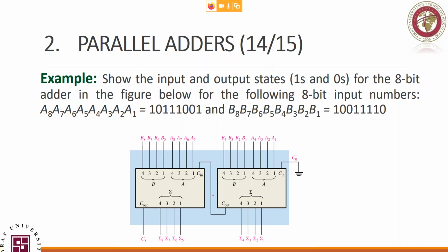You just need to apply the Boolean algebra arithmetic, or the type of Boolean algebra we learned, adding these bits and just accommodating for the intermediate carries and the outputs. Now, if you think about this one, just apply the Boolean algebra and that's it. All I can do is ask you about the carry, maybe in the truth table. You will just provide it in an easy way. Then it is just A1 plus B1 plus C0. What is it? 1 plus 0 is 1 with 0 carry. So this one is 1, 0 carry. Take it to the next stage.